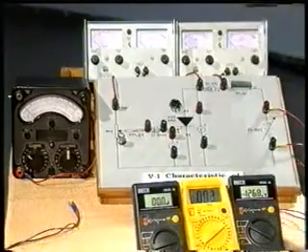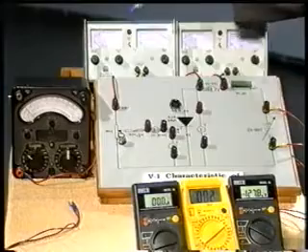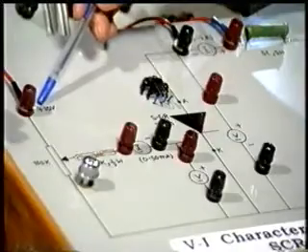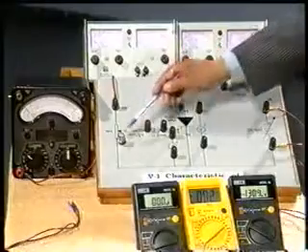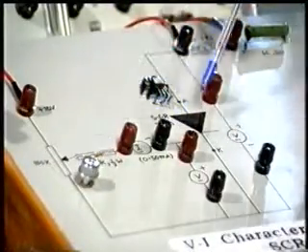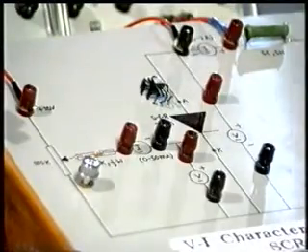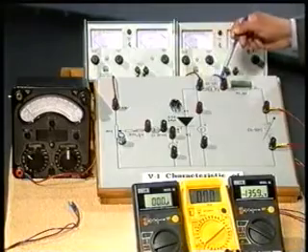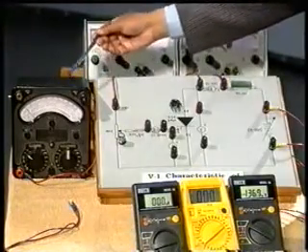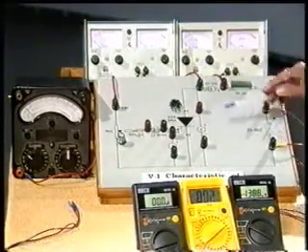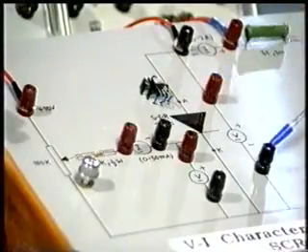Now, there is another power supply here. You can find that this power supply is feeding this point, which is nothing but the gate of the device, and the voltage here is constant 10 volts. With the help of this regulator, we are going to change the gate current. When we change the gate current, the device will start conducting at a particular point. Now, this resistor, which is a 5 ohm 5 watt resistor, is acting as a load resistor. These two terminals, you see there is an ammeter connected with this multimeter. This is being used as an ammeter, and it will show the current through the device. These two terminals, this is positive and this is negative.